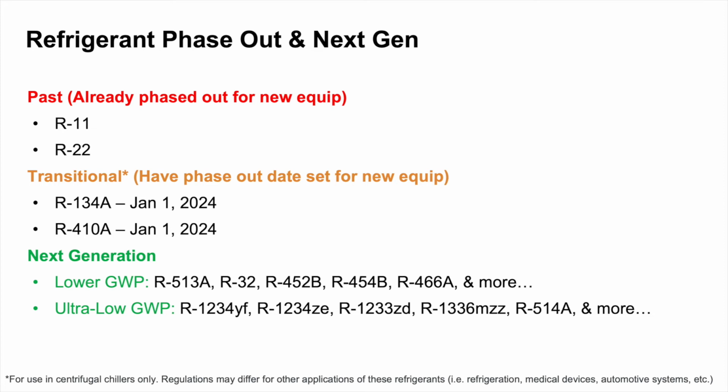Kind of red, orange, green goes to show bad, better, best. But right, refrigerants in the real world, this day and age here in our jurisdiction, that have been phased out and are no longer allowed to be provided with new equipment are things like R11 and R22, right? These are 15, 20 years old. They're still around. Like I mentioned previously, there may very well be equipment or facilities utilizing these refrigerants in place now and very well maintained, which is totally sufficient. But at some point, the existing refrigerant will be phased out, but there is certainly no new equipment being charged with this type of refrigerant.